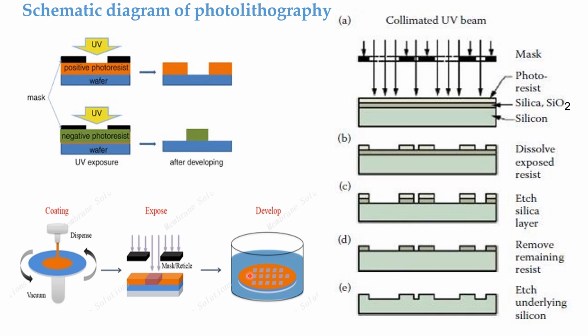microelectronic circuits. And this is how we can put some photoresist on the wafer, and this photoresist is a mask, and if we expose it with UV light, and finally this is developed in a solvent, and then we get the final structure on the wafer. So this was the photolithography technique which is mostly used in the semiconductor industry.